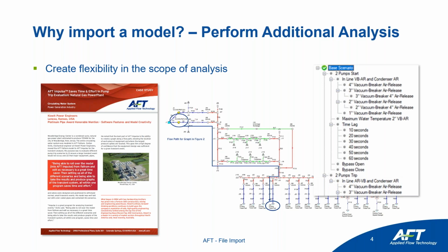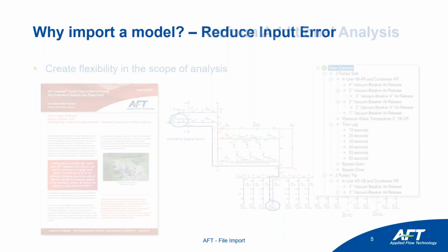They were then able to develop a lot of different scenarios, looking at different cases like pump starting and pump stopping, pumps tripping, what happens if these vacuum breaker lines are open or not, and then also if you add lag. So again, especially if you are an AFT Fathom user and you're looking at a surge analysis, it's very convenient to bring that steady state model that you've invested a lot of time and effort into an application like Impulse, where you can then define your transients on top of that steady state model. So we'll go through an example of that in the webinar a little bit later.